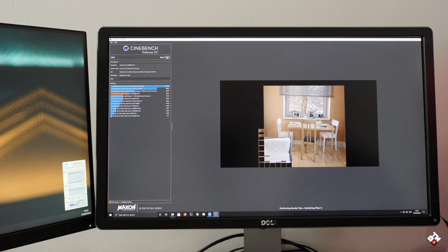Okay. Uh-oh. Uh-oh. It stopped. Yeah, the test has stopped. So at 5 gigahertz it's definitely not stable, either in Windows or on the Mac. Oh, actually, I can't even close this. So yeah, 5 GHz is a no-go on the Z370 motherboard, this particular motherboard.